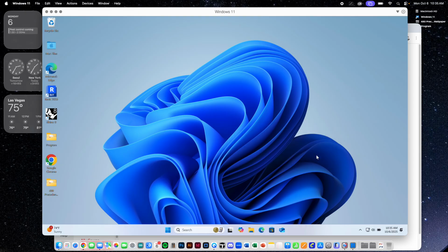I'm not sure exactly how you have that set up, but I have all mine here. I'm going to check a couple things. First thing I'm going to check is, do you have the units set to inches? Humor me. Sometimes I assume that, and then it's like, why is this cutting out really small or really large? It's because it's set to millimeters or feet instead. So let's just double check that. It's in inches, perfect.